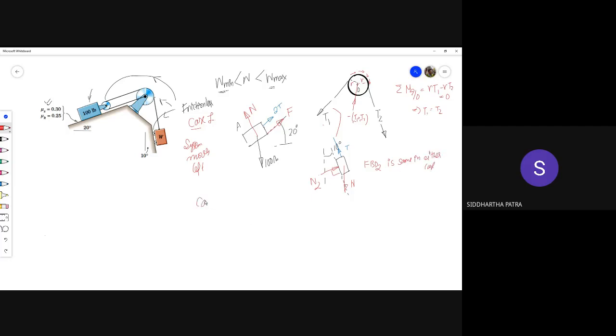But in case 2, the free body diagram of the first block will be different: the friction force would act in the opposite direction, when we are considering that W is pulling the 100 lb weight to the right. Okay, so that is when we are trying to get W max. You can do case 2 as an assignment, but can you at least get the value of W for case 1?